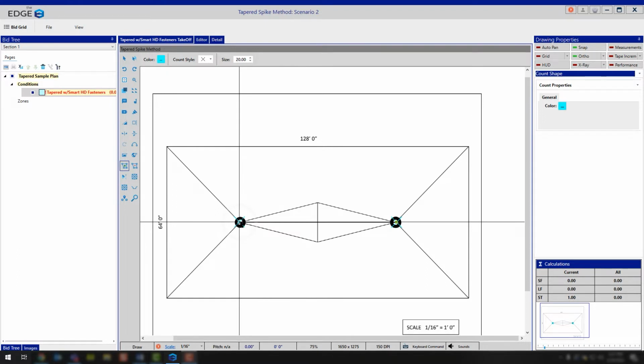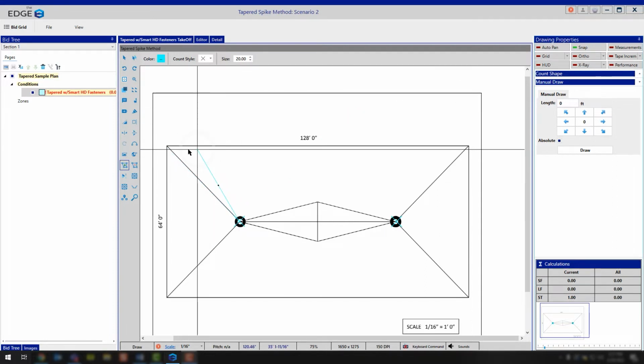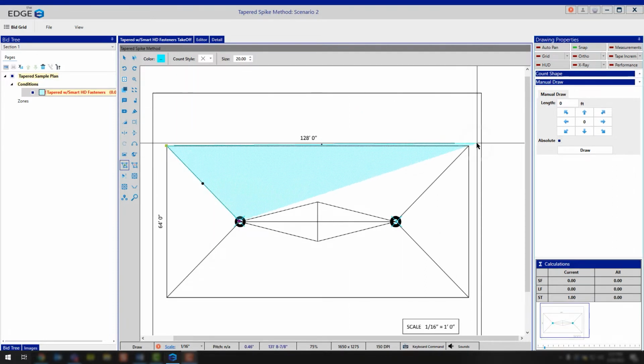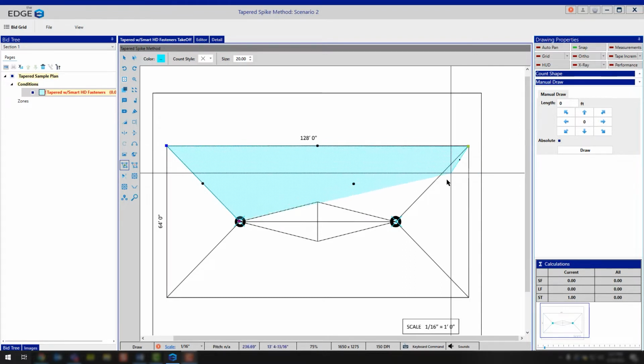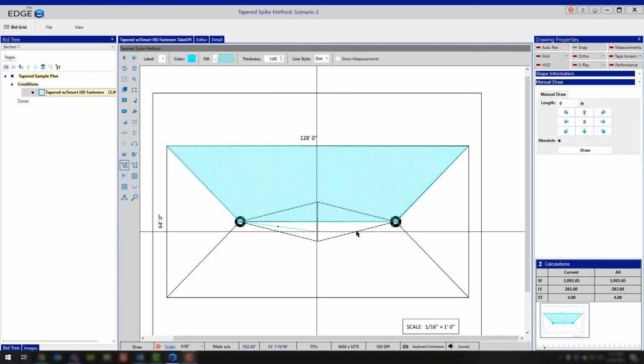In this case, you click on your area tool, and if you would like, you can start at the sump where you have your snap to points, but then you're going to simply follow along the image. Now in this case, you can see ortho isn't really working out for me, so I can temporarily turn the ortho off just so that way I can go in and make sure that I draw this to follow the lines of the image. Once you're done, click enter on your shape and then repeat.